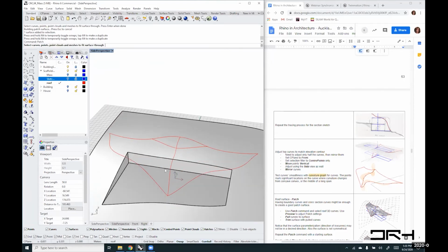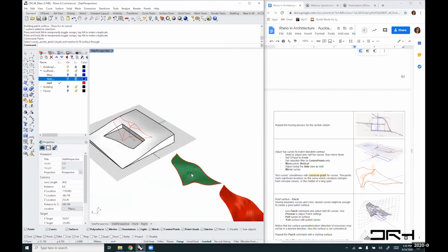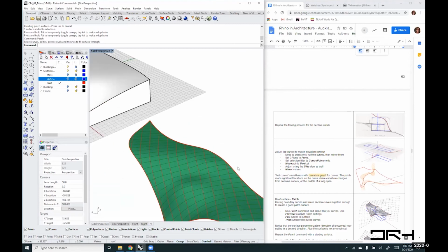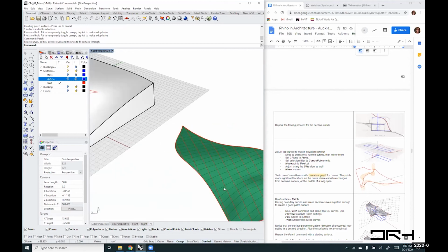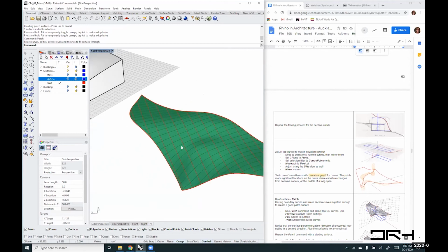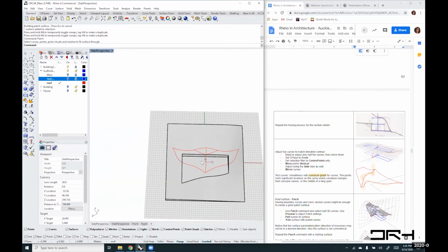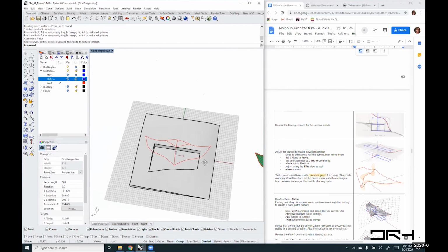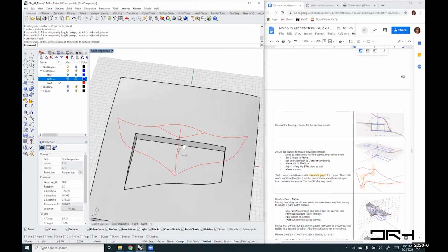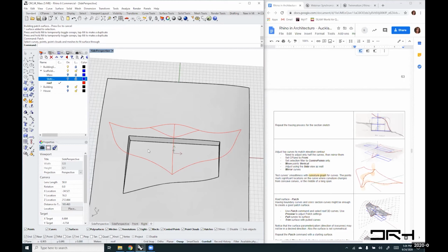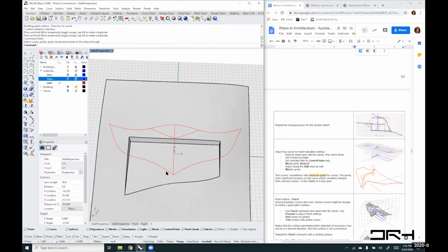The other thing you notice about these surfaces is that the direction of the parameterization, the ISO curves, is also not in any direction that is parallel or matching to our site. One of the things Patch lets you do is use a starting surface, and that gives a lot more clue about the direction of your parameters and maybe some of the symmetry information that we need.